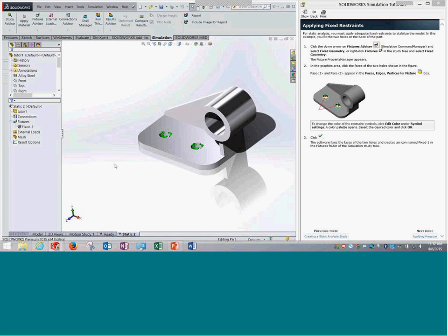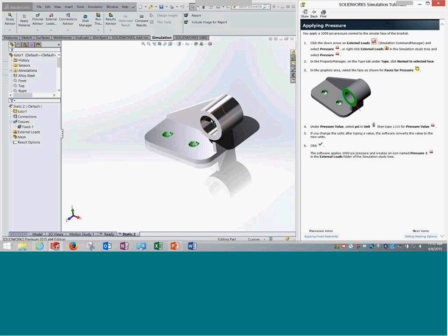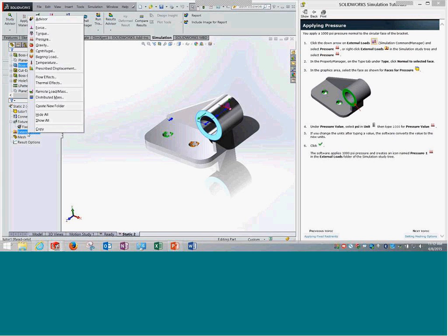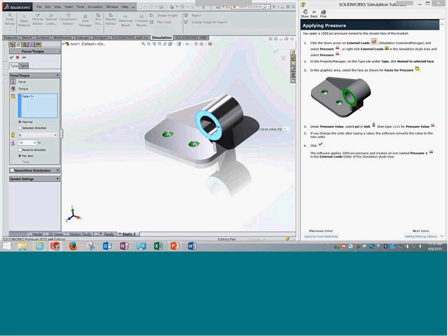Thereon, obviously I want to load this setup at certain locations. As shown in the image over here, the green part, that is this surface, I'm going to load with a force. Let's right click, force, and take a particular force. You have different options for selecting the units here.